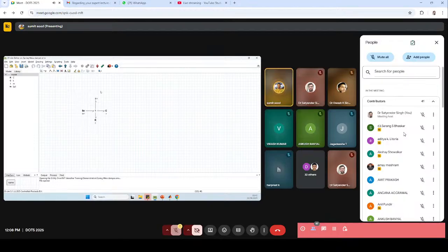Yes. So I have just drawn the same bond graph model for the spring mass damper system here. You can see there is a source of effort connected to one junction. There is 1 M, there is C and R, and you can see that there is no causality assigned here. In our case, we do not have to assign it ourselves. Once we process the model, it will be assigned automatically by the software itself. So this makes our work easy.